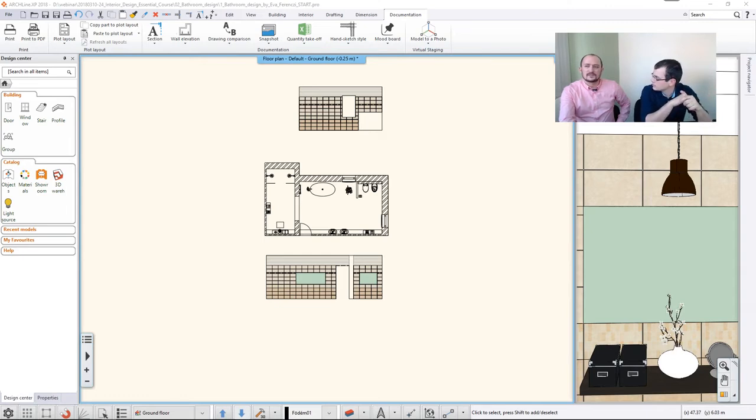Well, first things first, if you would like to make renders, you should make sure that the light is hitting your room. You need to set up lamps, just as we see in front of us now. You need to make sure it's a lamp, not just a downloaded object. We will cover this later, but when you download something from Google 3D Warehouse, the software is trying to figure out if it's a lamp or something else, and it is trying to convert it into a lamp if necessary. But other than that, you can also create your own library of lamps. You can just turn any sort of object into a lamp.